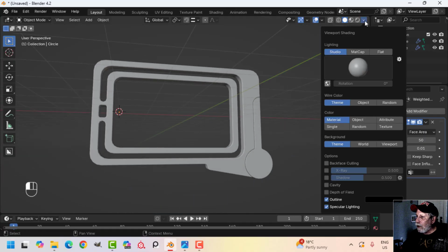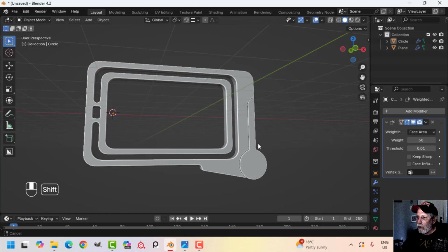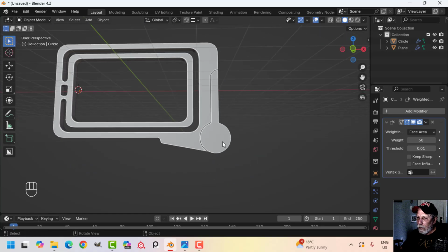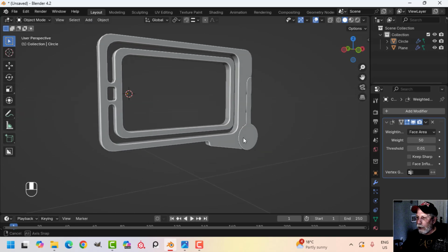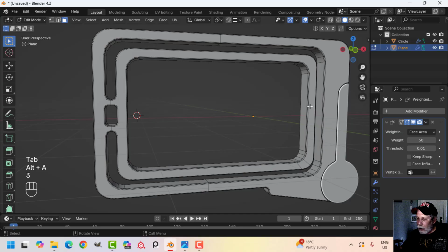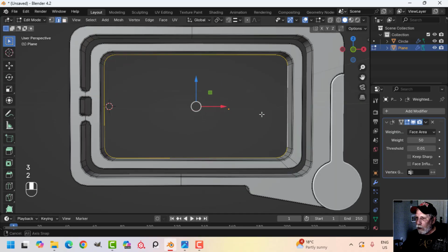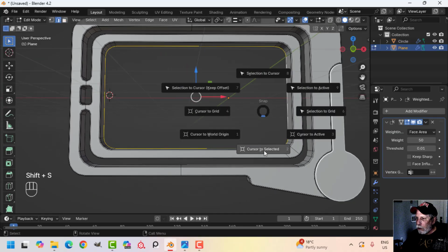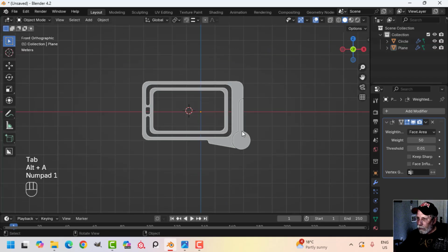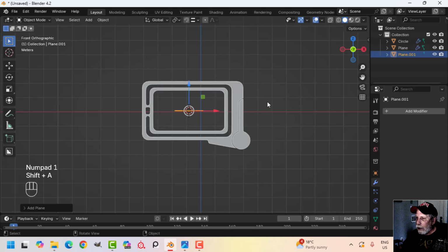Okay. So let's make sure we got the cavity shader on. It'll look a little bit nicer for us. All right. Yeah, we're doing what we can. Let's put a little screen in the middle by maybe selecting into edge selection, Shift Alt and click. Just bring the 3D cursor back there, right in the middle. And we'll look from the front and Shift A, mesh plane.